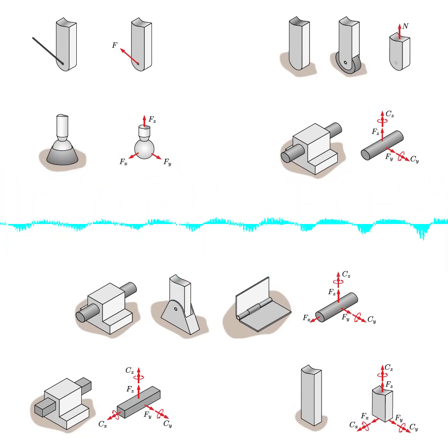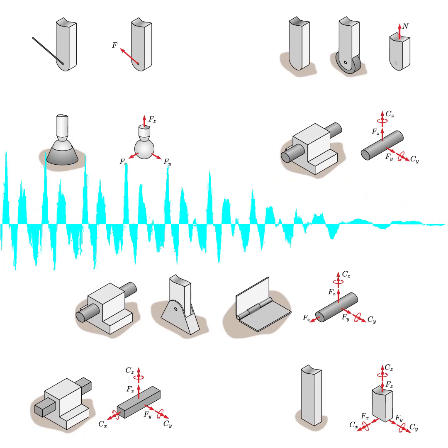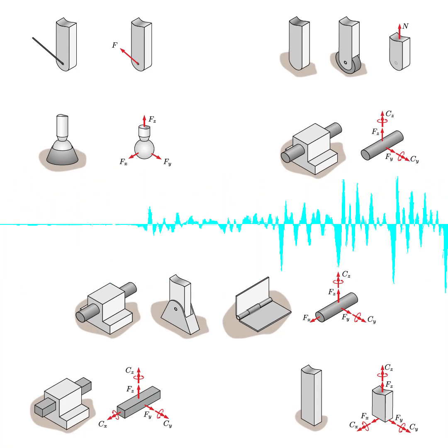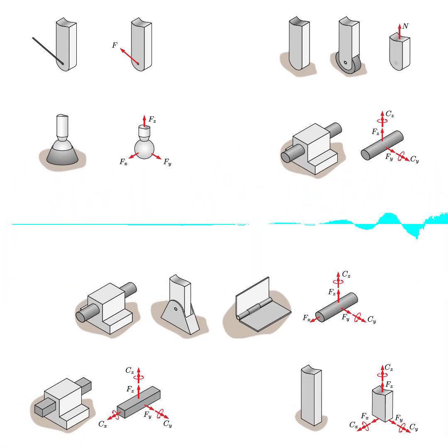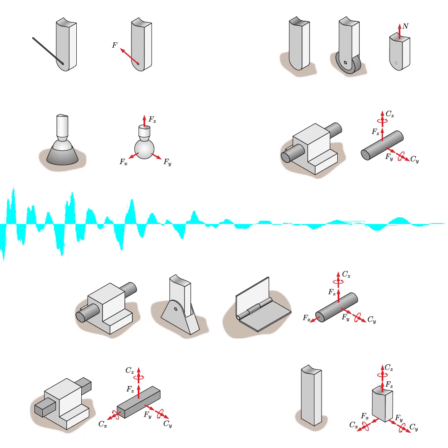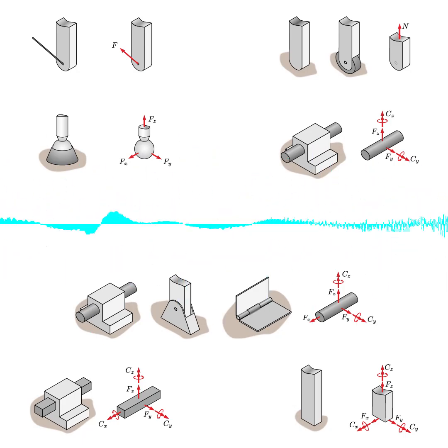One of the key strategies is to pick the point about which you're taking moments very strategically. So the textbook actually highlights that if you take moments about a point where two or more unknown forces intersect, then those forces won't show up in your moment equation at all because their lever arm is 0. So that can simplify things considerably. Sometimes you can even get an equation with just one unknown. That's a really good shortcut.